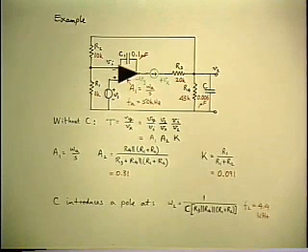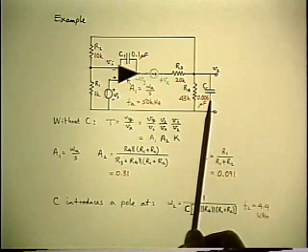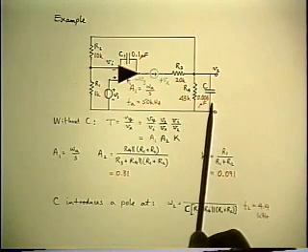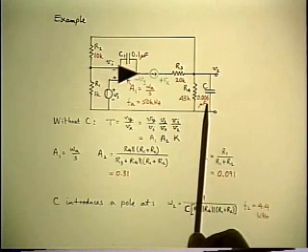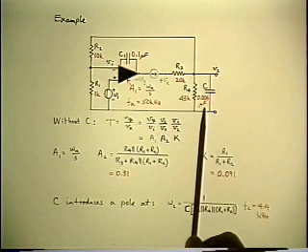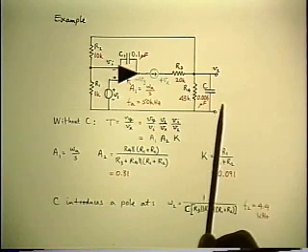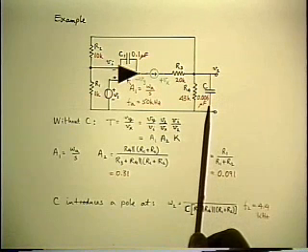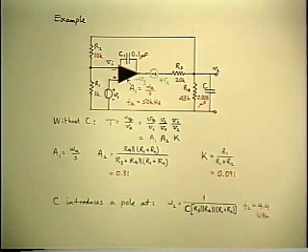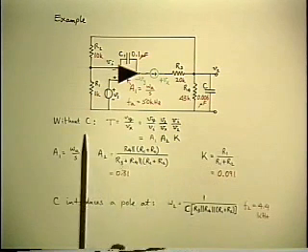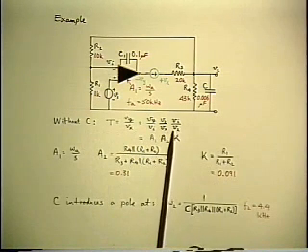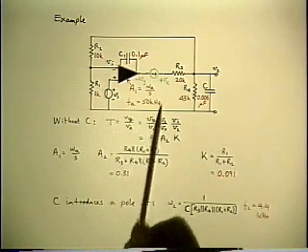Because it's going to give a pole and a zero, and each of them is going to be determined by the corresponding driving resistance. So all I have to do is calculate the driving resistance to find the pole, which is the RD, which is found under conditions of zero input and substitution of an independent source for the capacitor. And again, the only catch is you've got to be careful to identify properly what is the input. And we're solving for the loop gain. The input to the loop gain is the quantity in the denominator, which is Vx.